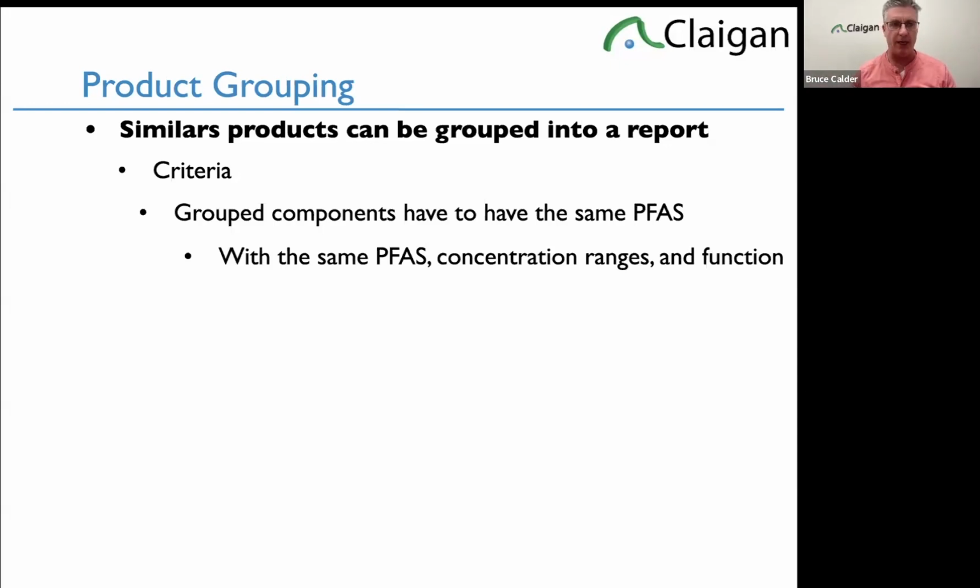Like the FEP in the wire will be between 10 and 30% of the weight. And the function, it's an electrical insulator. It's a high temperature electrical insulator. So you don't want to say just electrical insulation, because then everybody's like, you could use PVC. PVC can't survive the temperature your router or your stove handles. You have to use higher temperature, and that's why you use FEP. Why don't you use PTFE? Because PTFE is too rigid.